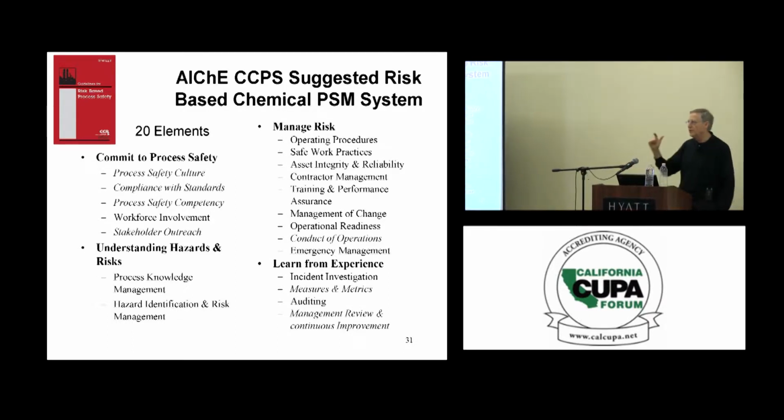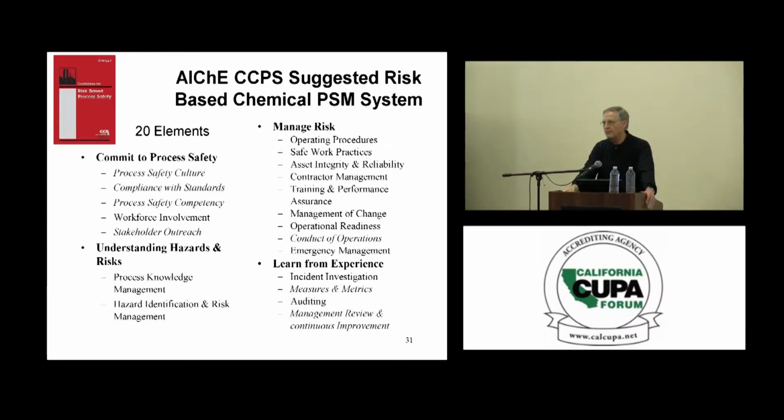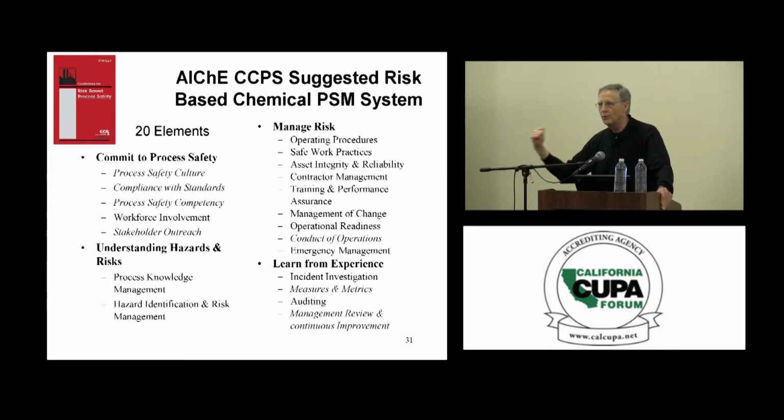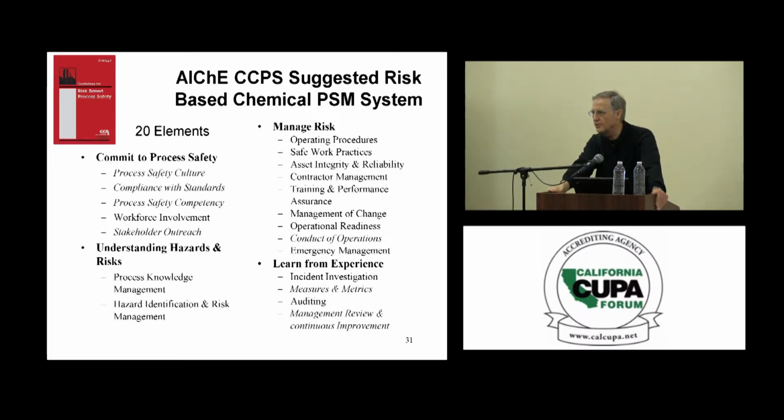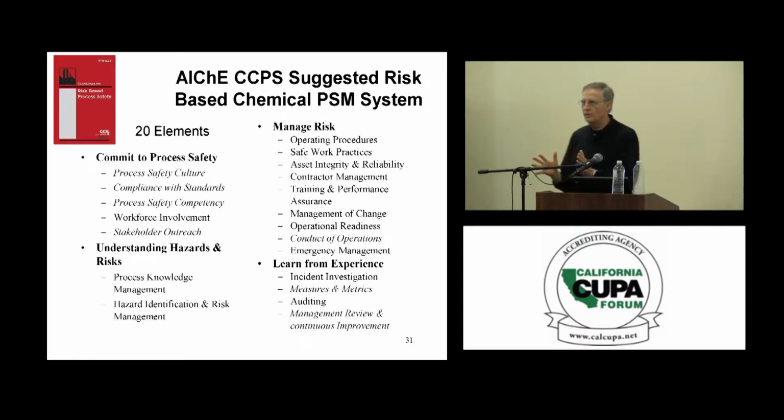And getting complacent and condoning deviations from standard procedures. They got into the habit, for a number of reasons related to mechanical integrity problems and poor design and poor maintenance of instrumentation systems, of deviating from the operating ranges. They operated up to 1400 degrees Fahrenheit, and one of the operators went out to look at the other set of instruments that they said we can only count on those being the accurate readings. And where were they located? They were located right at the base of the unit.